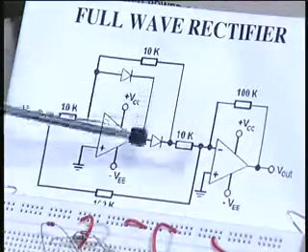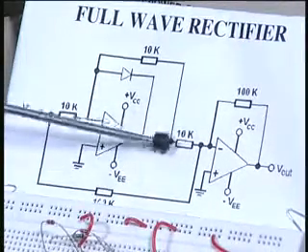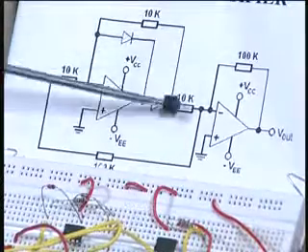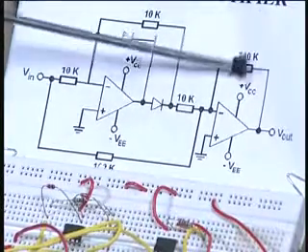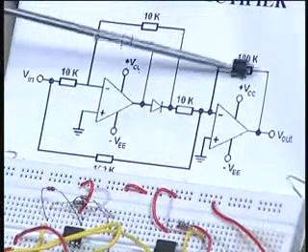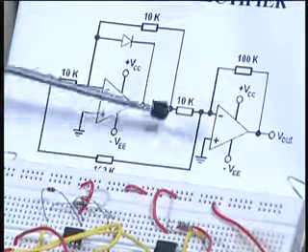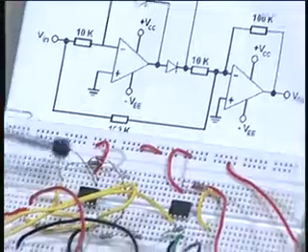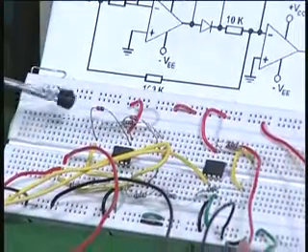Now the gain of the signal for the half wave rectified signal is 2. This is 10k and this feedback resistor will be 20k in the actual circuit, and similarly this will be 20k and 20k, therefore this gain is only 1. So now what you see here is the first op amp, in which I have used the diode here.